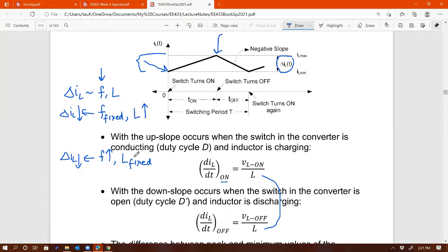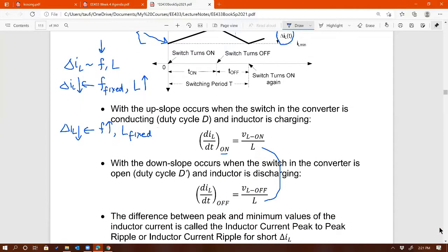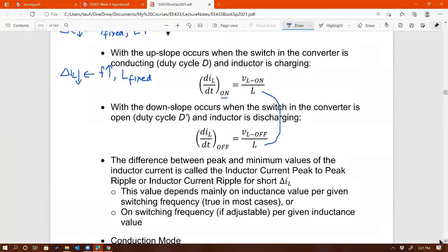And one of them is through soft switching. Anyhow, those are two main reasons why we cannot just keep increasing switching frequency. Number one, physical limitation of the device. Number two, switching loss is going to get big, again because of non-idealities of these devices.